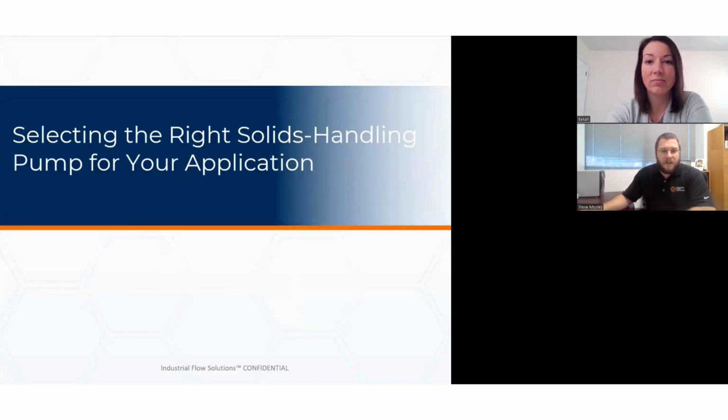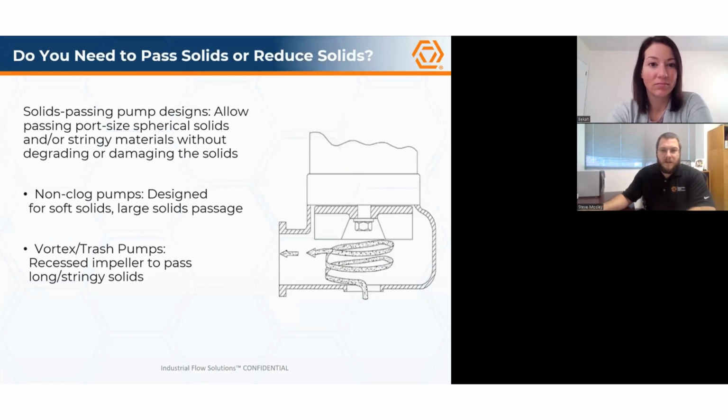And now we're looking at selecting the right solids handling pump for your application. The question of solids passage versus solids reduction can come up in many applications due to the wide variety of items that can get flushed or washed into a wastewater pit. In the past, the main school of thought was to pass these solids whole to allow them to be caught on a bar screen at the treatment plant for easy removal.